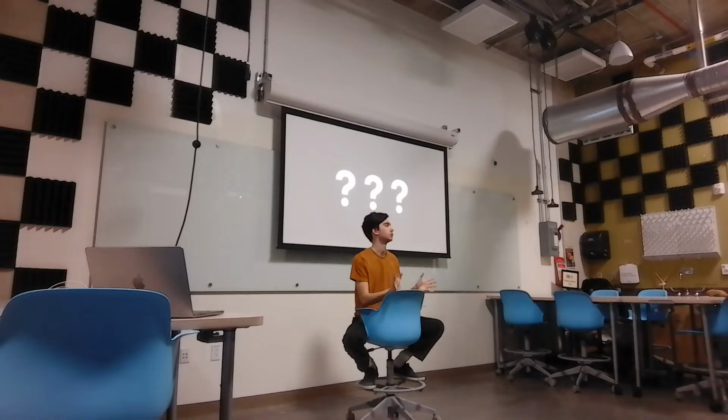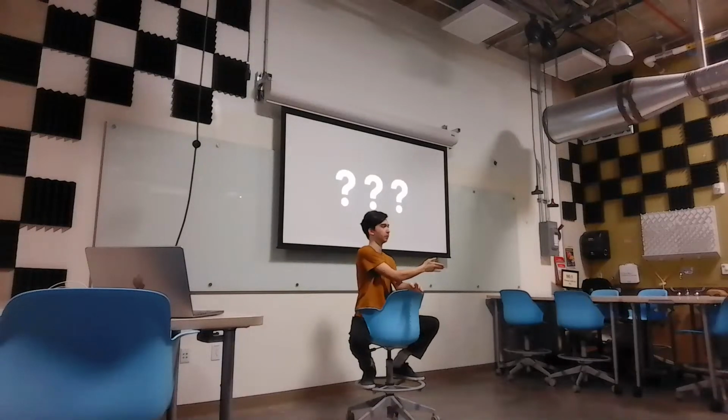It just picked the closest. Think about it, there's two possible voltages. We're here, so we're good. But if these slowly start going down, it's still picking the bottom one, and then halfway it goes to the top. You discretely switch it, and that's visible. There's only 160 levels, and since it's an LED, only the top 50% of them are useful, because all of them below 4 volts are off.